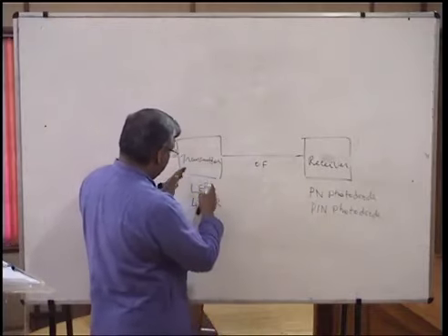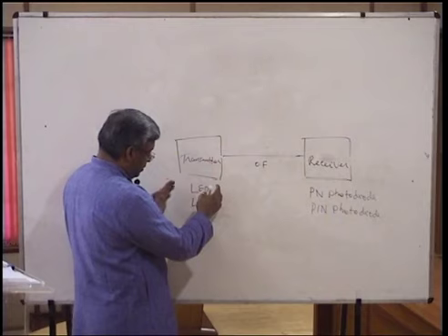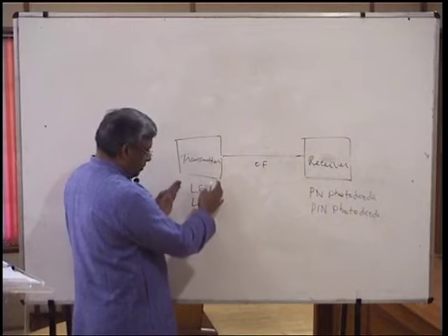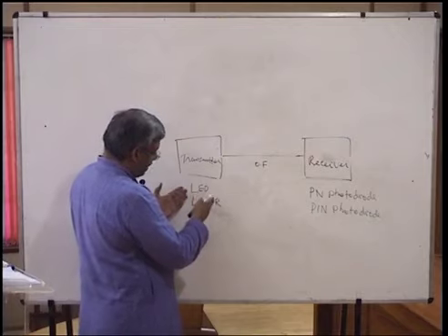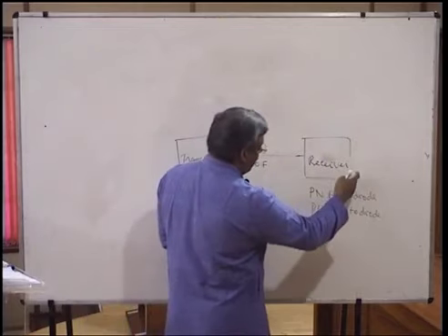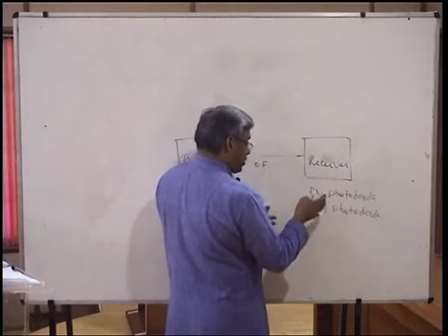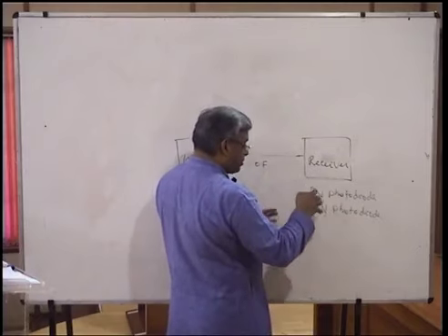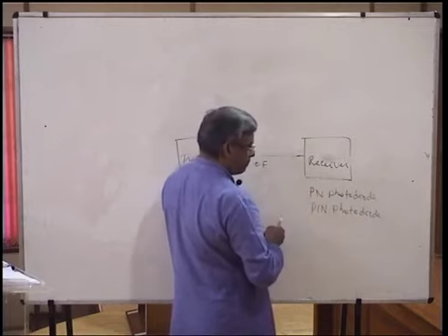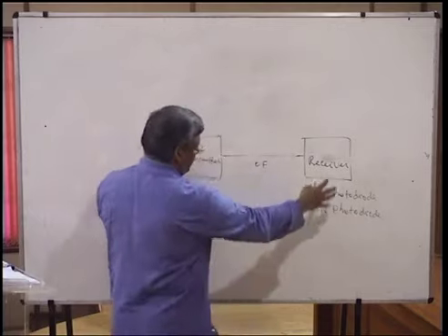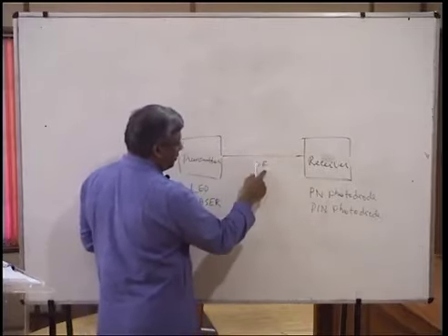So once again, the transmitter side will be constructed by a semiconductor PN junction, which is forward biased externally. The receiver side will be equipped with another PN junction, which is reverse biased externally, acting as a detector of this particular signal. This is how the total photonics works, and tomorrow we'll be coming back to discuss optical fibers.